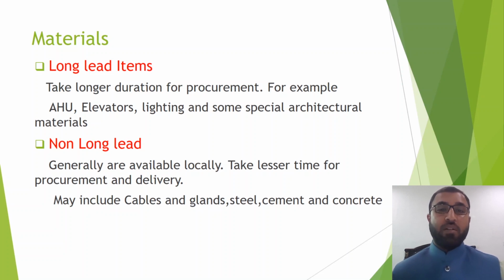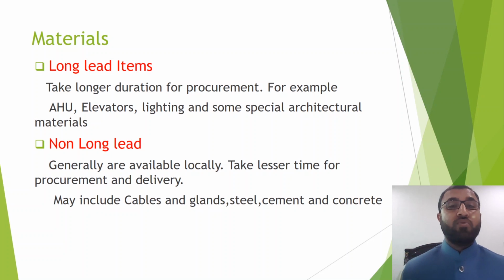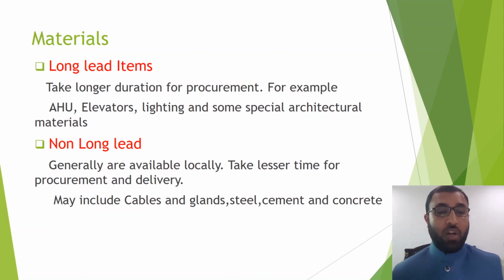You need to consider their duration because they will be more critical. If any delay happens to them, definitely your construction activity is going to be delayed. If it has some float, then it is going to eat that float. And if it doesn't have any float, then obviously it is going to delay your project. Non-long lead items generally are available locally and take less time for procurement and delivery. They may include cables, glands, steel, cement, concrete. So these are all non-long lead items.